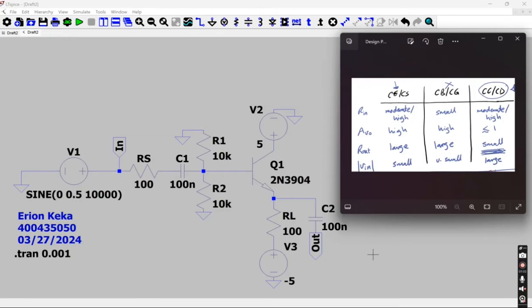Furthermore, upon comparing the amplifier stages of both the BJT and the MOSFET, we notice that the amplifier stage of the BJT is more linear due to the gain being independent of the bias voltage. Also, the BJTs feature a higher gm value compared to the MOSFET. This is due to the BJT being a current-controlled amplifier rather than a voltage-controlled amplifier like the MOSFET. Thus, irrespective of having a slightly higher power draw, the BJT can produce an output featuring a higher fidelity compared to the MOSFET.